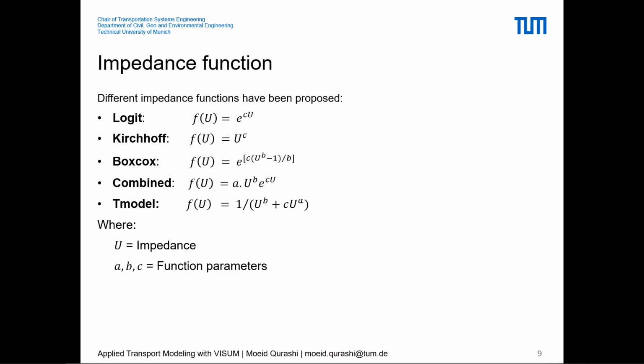And once you get the value of C and do the trip distribution, you get an OD matrix. Then we'll try to model a TLFD. I will give you the concept. But the value of C we are calibrating is exactly the error that we will have. We calibrate these parameters from the observed trips and use them in the model. Once we get the model output, we compare it with the observed and get an error, say 95% or 96% is represented. So this error arises when we calibrate this impedance function.